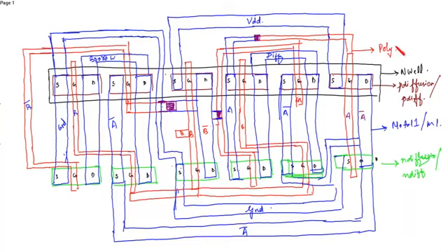Okay. Now you have to place the contacts. That is, in order to make a contact between the P diffusion layer and the metal, you have to place a PDC contact.